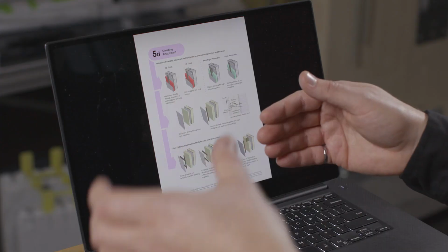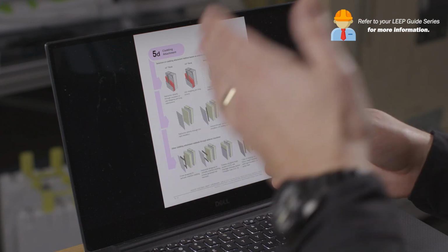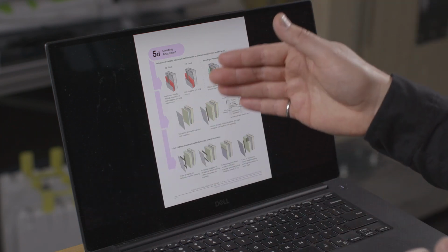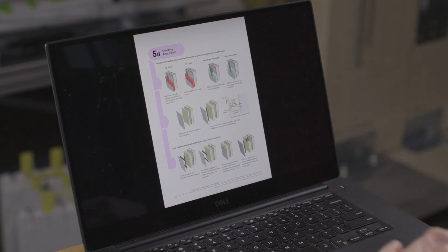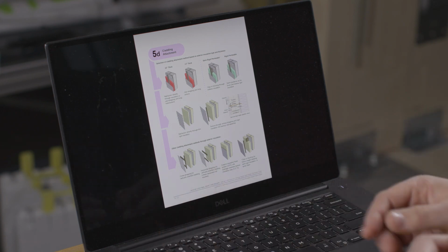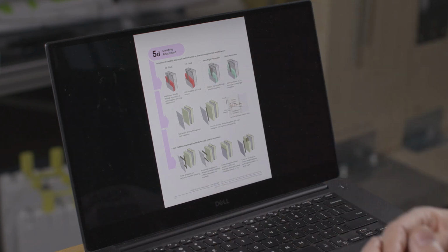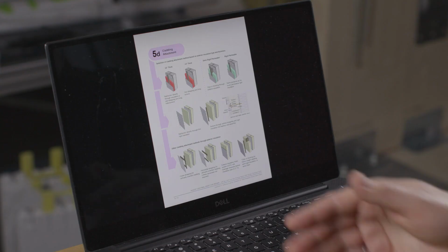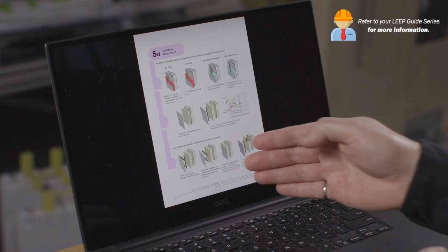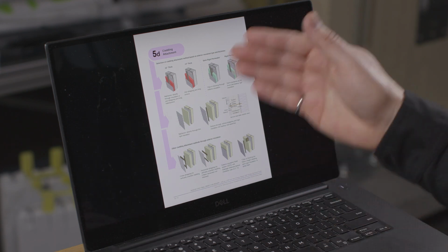And then it was talked about in the last part here. So we've got our insulation, we've got the water and air barrier placed, the vapor barrier, then how do we attach cladding? With thinner or thicker amounts of insulation, there's guidance here around that. And it talks about long screws through insulation and how you attach cladding to strapping that is screwed through your insulation for thicker amounts of insulation. A number of alternate configurations are also talked about. If you have, say, vertical board and batten or shingles, things like that, where you need horizontal strapping, how to do that. EIFS is talked about, and heavier claddings are also mentioned in here as well.